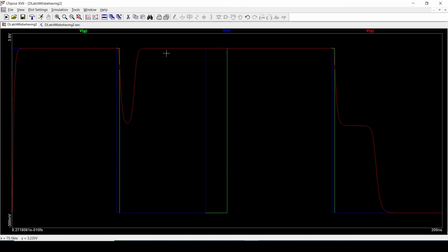When the gate is a 0, remember the D latch at the RS latch side at the end just looks like 2 inverters connected in series. And so with 2 inverters connected in series, the output will either head up to a logic 1 or down to a logic 0, depending on which side of the border they start off at, so to speak.